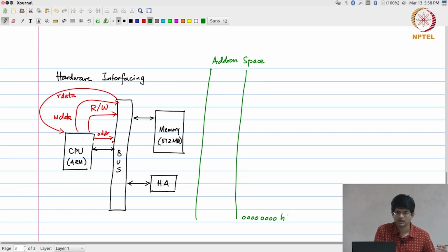It's much easier to understand an address space when we are talking about hexadecimal. Why? Because it makes a lot of the sort of sub-memory calculations, etc., a lot easier. Okay? So, in general, when I am talking about memory blocks, it's going to be in hexadecimal, right? It starts from 0, and for a 32-bit bus, the highest possible address is all Fs, right?